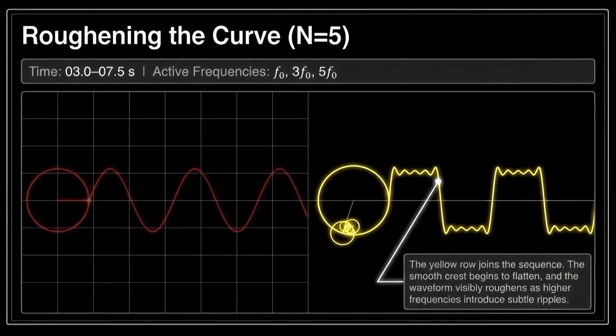It all comes down to phase alignment and interference. When we stack these odd harmonics, the 3, the 5, the 7, we aren't just throwing curves into a blender randomly. Right, because they are very specific multiples. Exactly. Because they are specifically odd multiples of the fundamental, their peaks and zero crossings align in highly specific, rigid ways. Oh, right, because if we were adding even harmonics like 2 or 4, it would just break the symmetry, wouldn't it? They would. It would push the wave to one side and give us something like a sawtooth wave instead of a square. Exactly. Odd harmonics preserve what we call half-wave symmetry, which is an absolute requirement for a square wave.